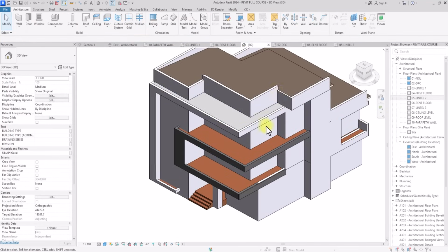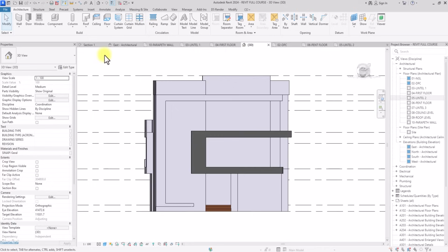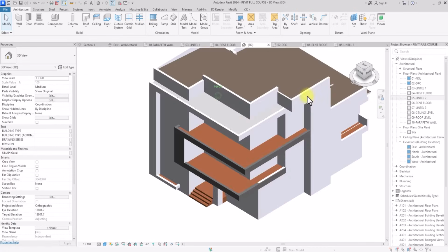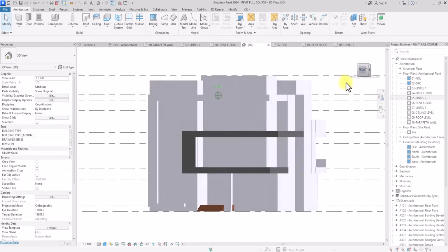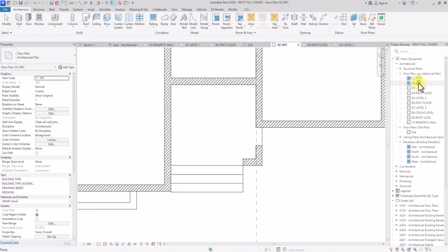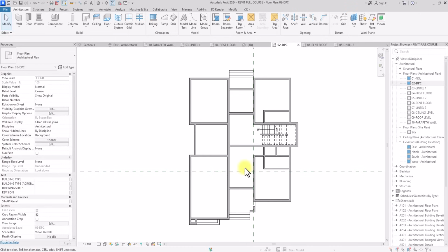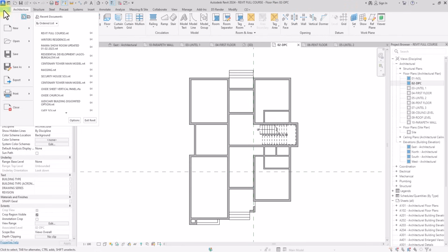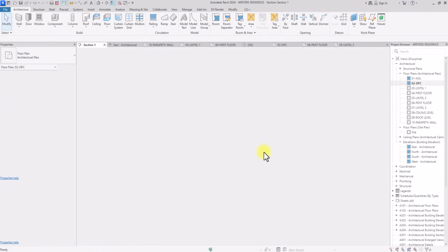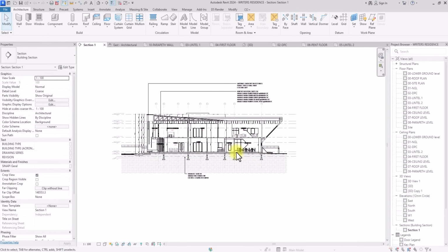We are now going to enter the fenestrations and maybe the material applications and the color of the building. So this is when the design aspect starts coming more into play. Of course, I'm going to start from the ground floor, that is DPC. While working on fenestration, doors and openings, we always start from the DPC instead of the NGL. What I usually do for fenestrations is go to an already existing project I've done before,